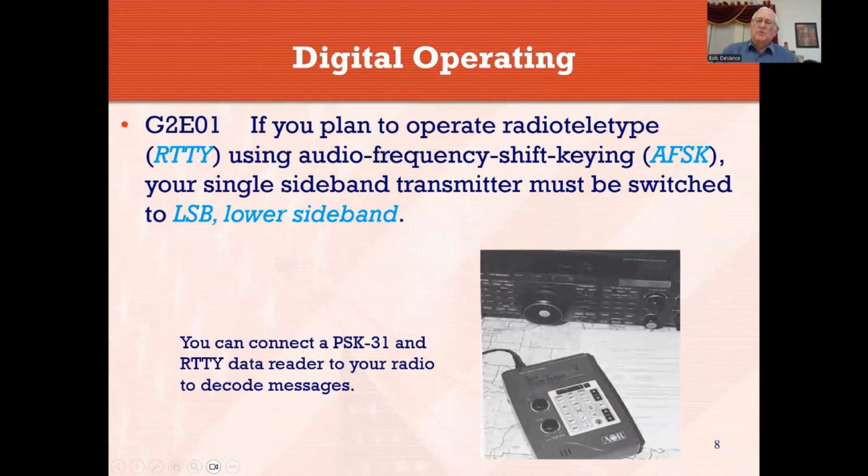Okay, audio frequency shift keying is what we use on radio teletype, RTTY. Audio frequency meaning that we have those two audio frequencies and we shift back and forth between those two frequencies. One of the peculiarities for radio teletype is it always uses the lower sideband. Doesn't matter which frequency you're on. Normally we use LSB for 40 meters and down, and we use upper sideband for everything higher than that. But for radio teletype, everything is done lower sideband.